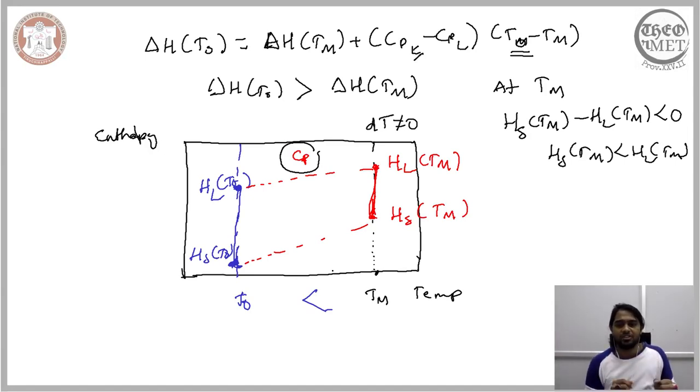So what we have shown in this theoretical consideration is that the driving force for solidification at 0 degrees Celsius, like we considered in a few slides before, will be lower than the driving force for solidification or freezing at minus 10 degrees Celsius. That is the understanding we gain using this difference in the enthalpies. So with this, we will wind this lecture up, or we will wind this module up.